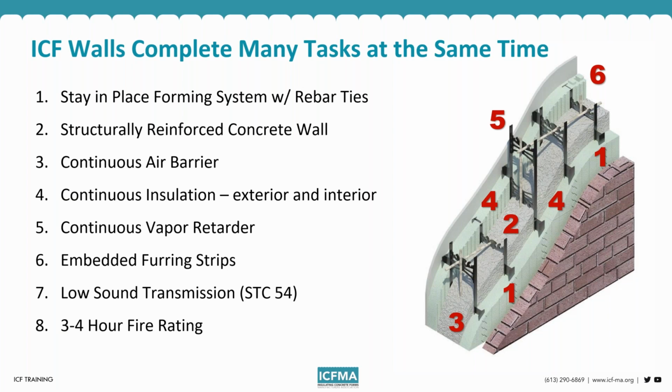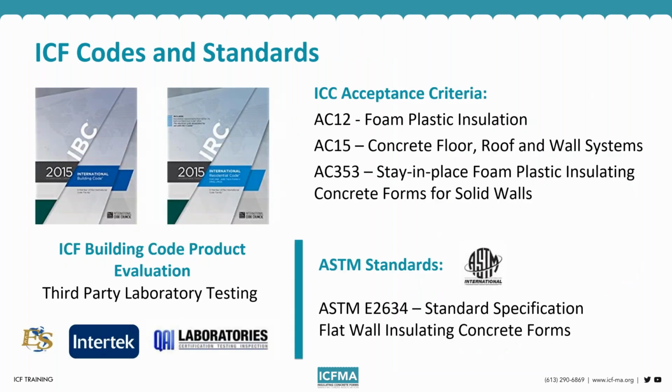ICFs also have a low sound transmission rating, often rated up to about a 54 with a 6-inch wall, and ICF walls are also well known for their fire ratings, typically rated between 3 and 4 hours. ICFs are also well adopted in the code, and so we are adopted in the IBC and the IRC.